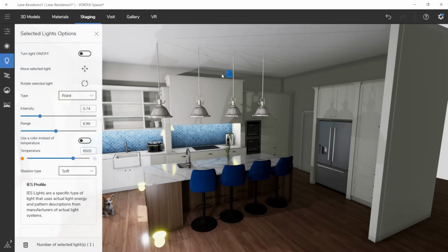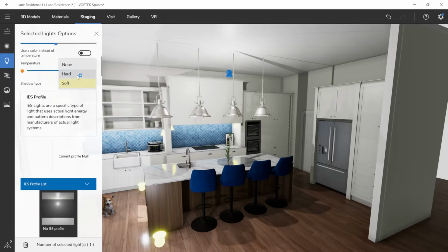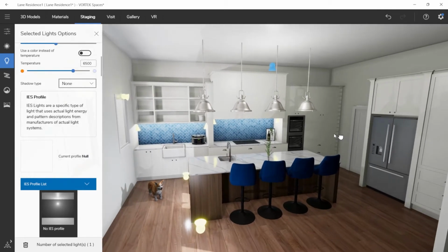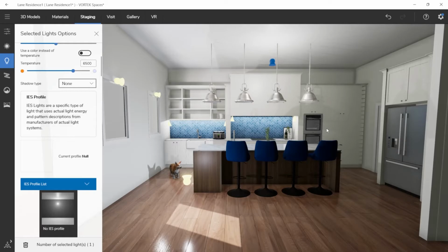After that, here, that light in the ceiling is one trick that we use sometimes. When you're done with the lighting, you can just add 1 light. It will be about 30 to 45 centimeters from the ceiling. And then this one here, I'll just put no shadows. So it will erase a lot of the shadows that are unwanted inside of the project, but keep the whole effect of the light coming from the exterior of that scene.